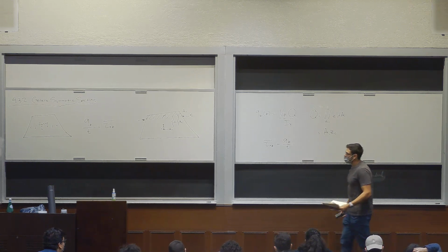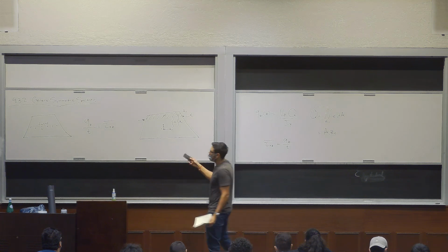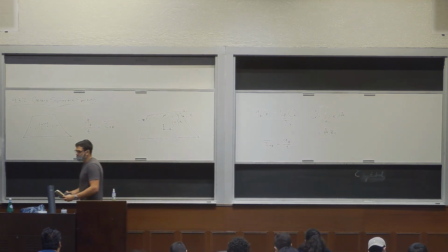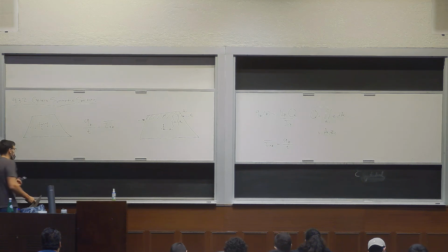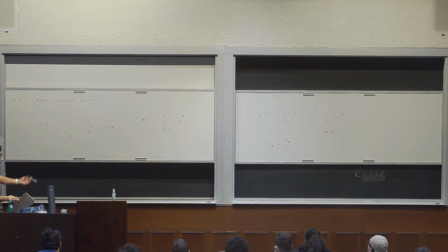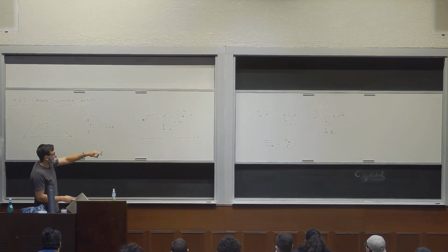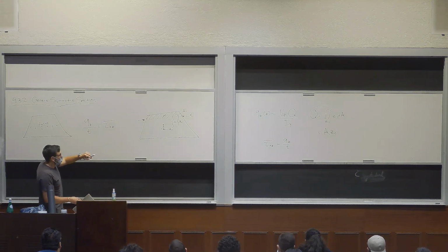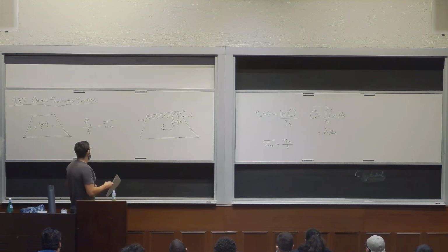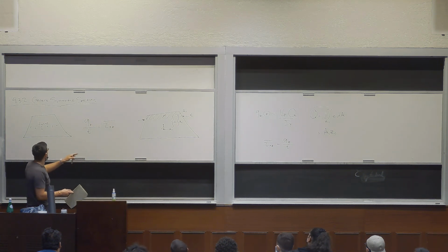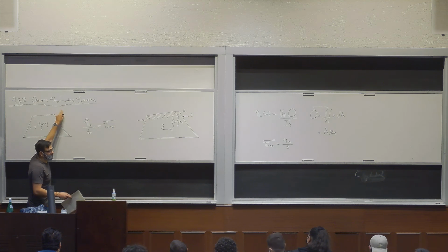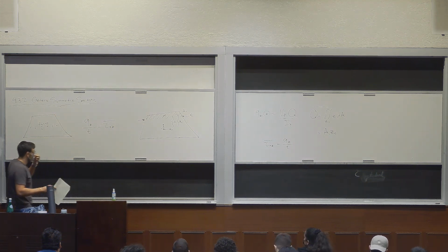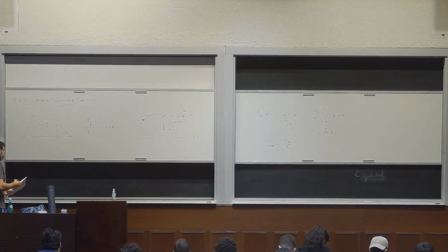So in your final exam, you probably want to encounter a problem like this with these solid sections. These solid sections are not too relevant to the aircraft structures that you'll be analyzing. Typically, we'll be doing these spar web structures, so that's what I'll be covering next, or thin-walled structures. However, this equation, VZQ over Iy, is basically how it's done even for the thin-walled sections and for the spar web sections. The only difference is, keep in mind that these equations that I've derived here are still for symmetric sections. It's not the most complex version of them, and I'll get into those, but just for the sake of explanation, again, that's how it's done.